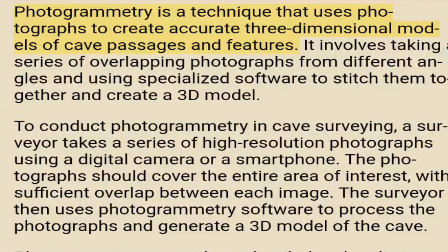Photogrammetry. Photogrammetry is a technique that uses photographs to create accurate three-dimensional models of cave passages and features. It involves taking a series of overlapping photographs from different angles and using specialized software to stitch them together and create a 3D model. To conduct photogrammetry in cave surveying, a surveyor takes a series of high-resolution photographs using a digital camera or a smartphone.